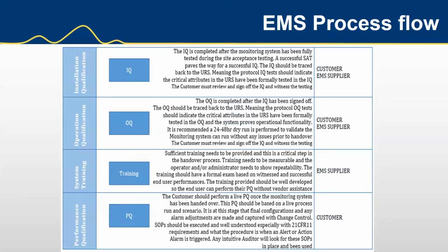The performance qualification, I'll really emphasize, and we're going to spend a bit of time going through this during the presentation. The PQ should be carried out by the customer. And please, please, please, please, please do not rehash the OQ. The OQ is a separate verification. What you should be doing is writing your PQ, test every aspect of the weaknesses of the system. You want to be trying to shake the tree and see what apples fall off if they do.